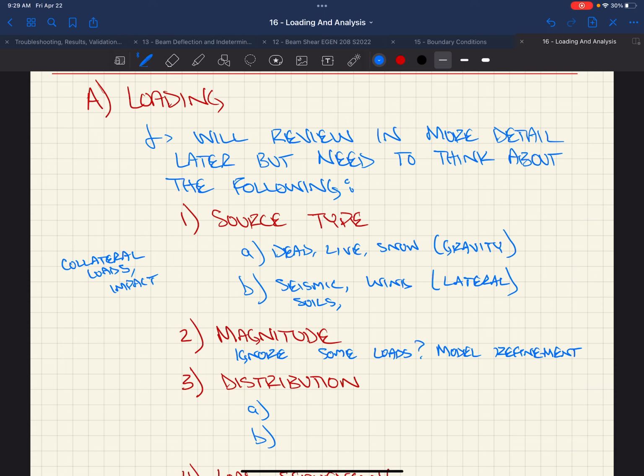I feel like more commonly it's moment and axial, where the same max thing wouldn't work, because axial would reduce your moment or increase it. So definitely with columns, like PM interaction diagrams, there would be a function. You can't go max axial, max moment. That would almost be unconservative sometimes. We've got PMN, and you're going to plot your PU and MU somewhere in the middle here.